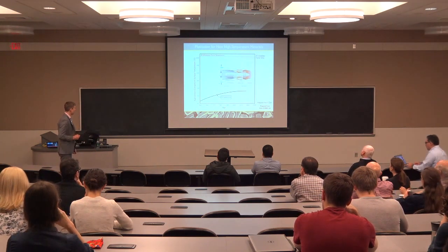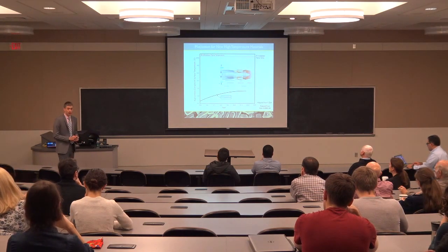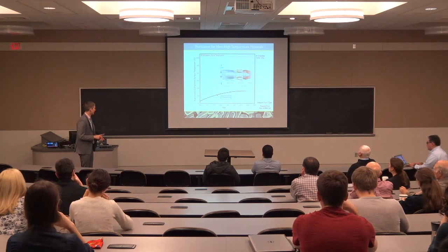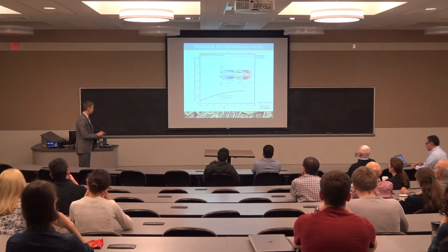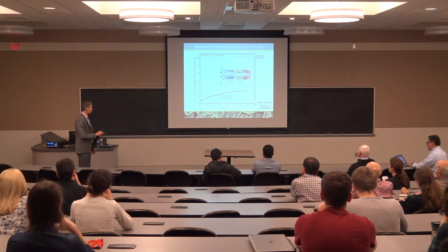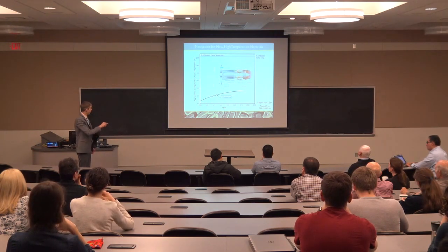And the big challenge in that are the materials. So if we think about where the adiabatic flame temperature is for jet fuel, it's up here above 2,000 degrees Celsius. We need to build the engine out of something. And the conventional material of choice have been these nickel-based superalloys. And this shows roughly the evolution of the temperature capability of those materials. We see that there's a big gap.